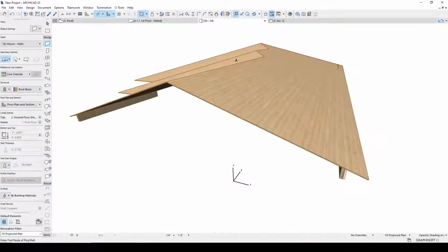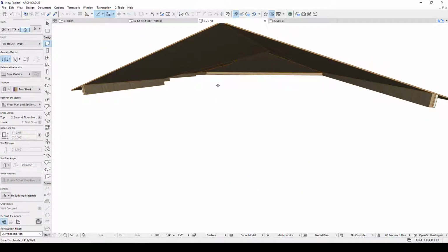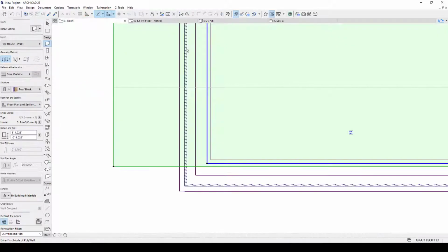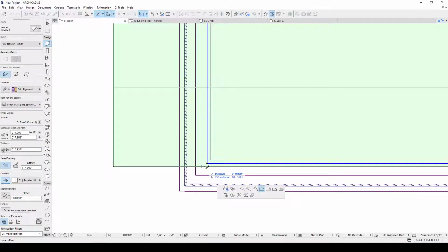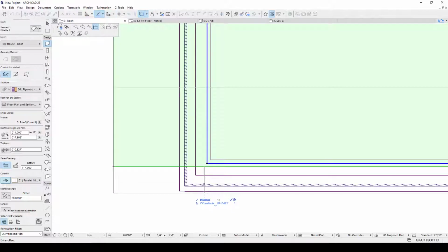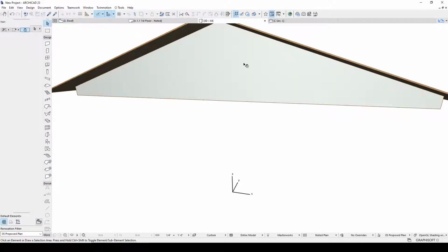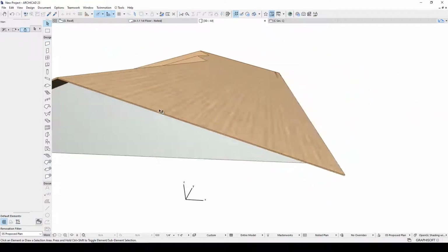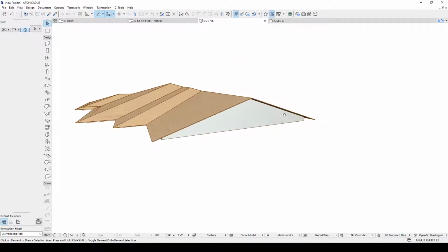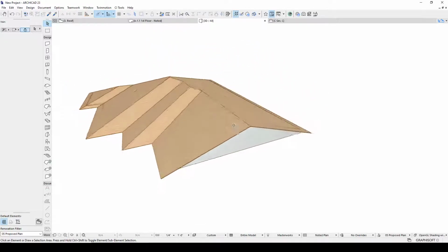Let's look at that in 3D. There's our gable. Okay. Now I want to manipulate, I'm using just my standard polygon tools. I want to manipulate the boundary, and I can do that separately. Now it brought my gable end back, which looks perfect. And so because the roof and the walls are associated with one another, I have the ability to continue to model, and everything will just continue to update nicely.